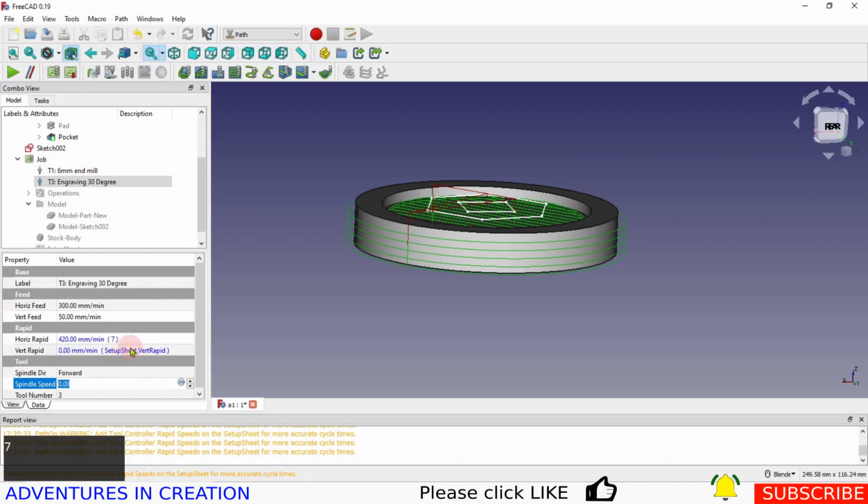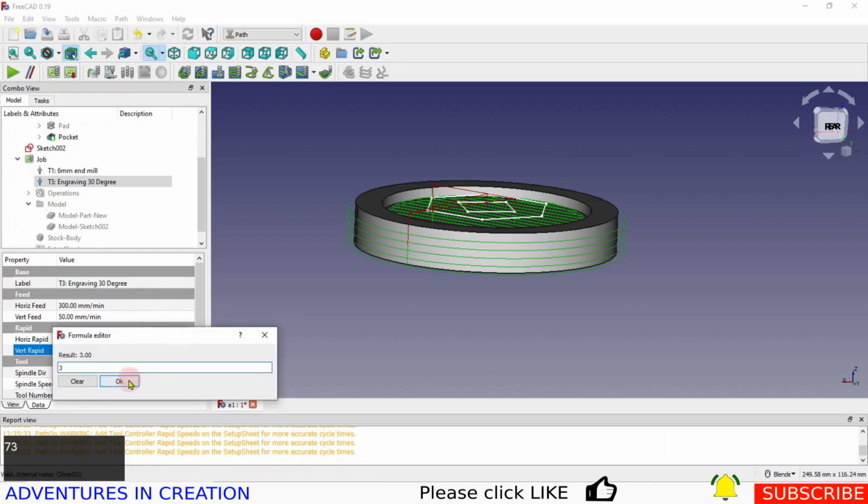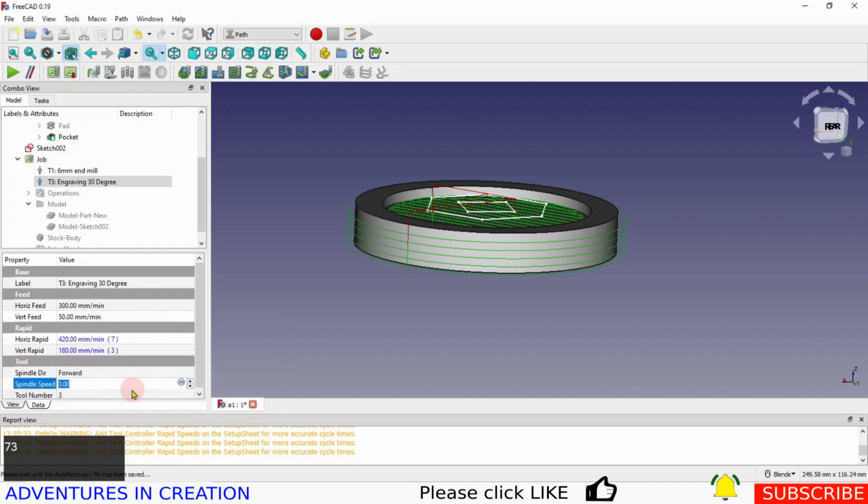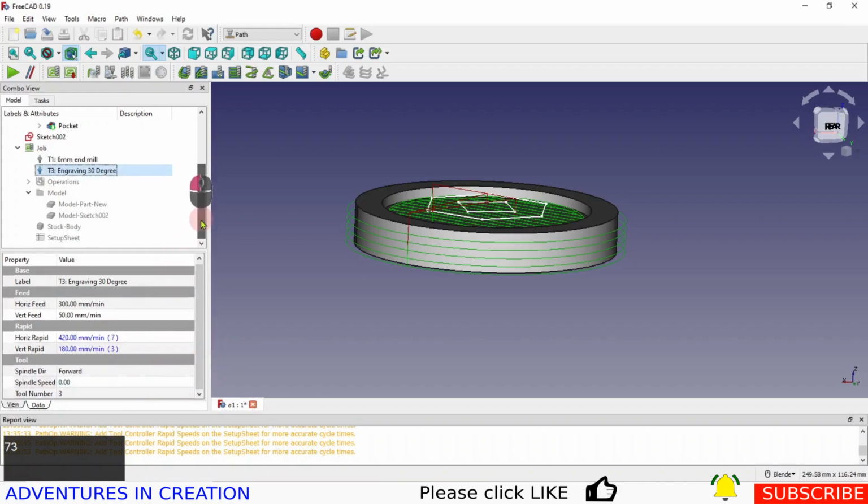So that will work. And then the same for the vertical rapid. I found a 3 gets me close to where I want it to be. That's 180. If anybody knows why they come up with those odd numbers, please let me know. I have looked at the setup sheet and modified it there, but even then, the horizontal modified correctly, but the vertical still did some weird calculation. And I'm not sure what is actually going on there, but I sort of did a workaround. If I use those numbers, I come out with more or less what I want.